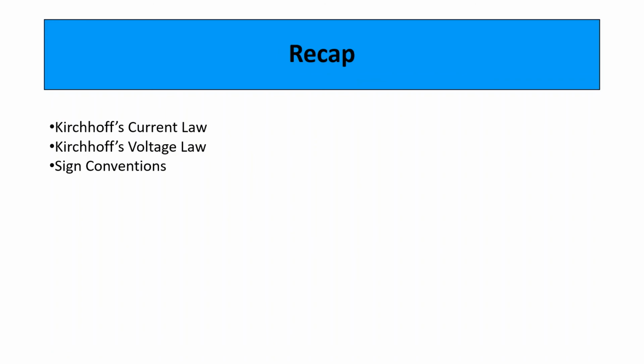In this session, we learn about Kirchhoff's laws. Kirchhoff has given two rules based on the conservation of electric charge and of energy. The first law, Kirchhoff's current law, is based on the conservation of charge. And the second law, Kirchhoff's voltage law, is based on the conservation of energy. Kirchhoff's current law states that the algebraic sum of the currents into any junction is 0. Whereas Kirchhoff's voltage law states that the algebraic sum of all the voltage drops around any closed loop is 0.